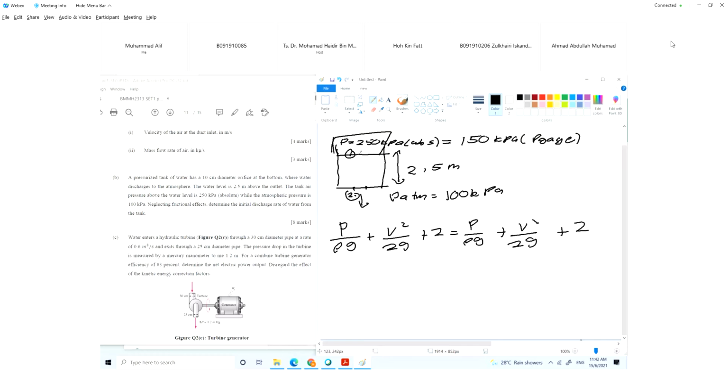Okay, so next, go to V. For the velocity, I hope you can understand in which case you can cancel P. You can cancel P at point 2 because the pressure at point 2 is P atm. So you can cancel P2, but not P1 because the pressure is 150 kilopascal. Now we go to the velocity. Velocity at point 1: it is a tank, where you can assume the velocity is too low because the tank is too large, so cancel V1. But at point 2, the area is not too large because you already know that the orifice is 10 centimeter. So where's the question?